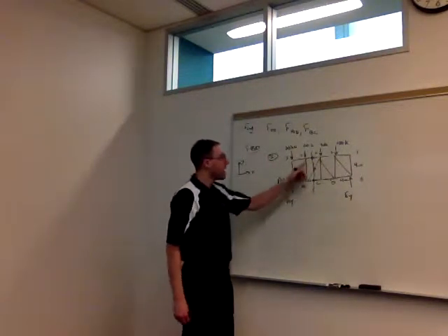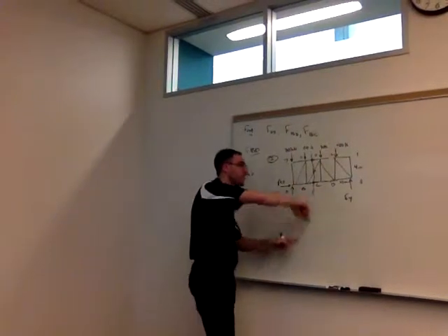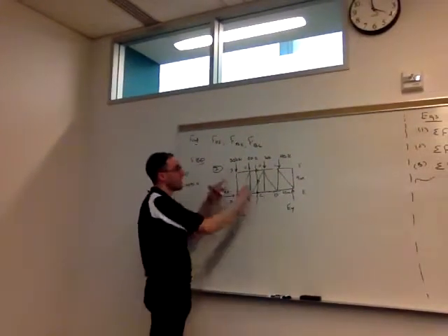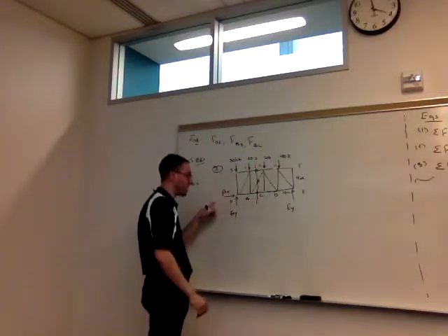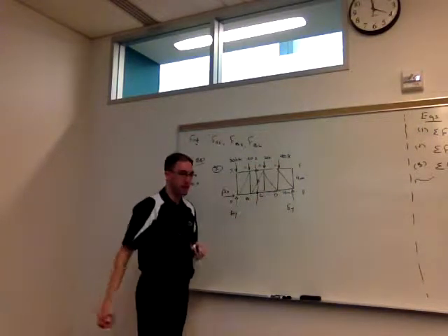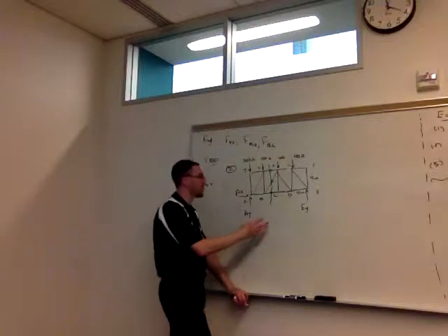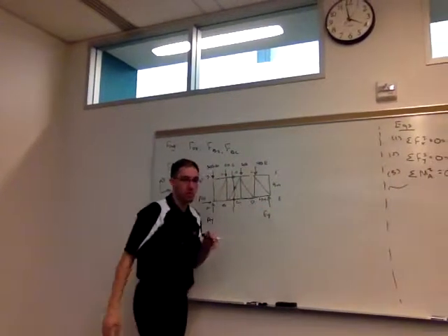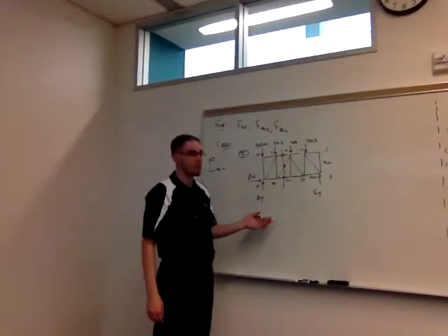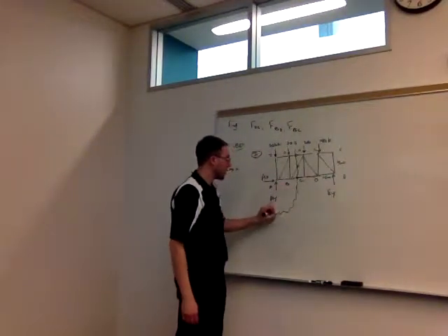Here it doesn't really make much of a difference if I loop to the left or if I loop to the right. I'm going to have 2 applied loads either way. AX happened to be 0, so I'll have one reaction force either way. In some problems, though, it's much more obvious that you can take a much smaller picture rather than the much larger picture. You're going to get the same answer either way, but it's just less work.